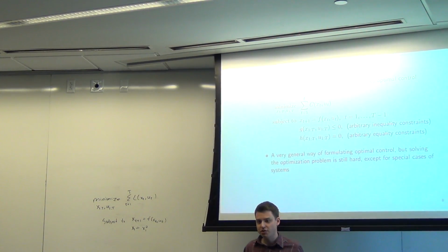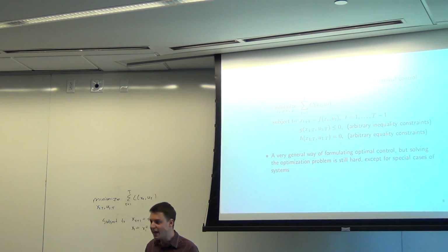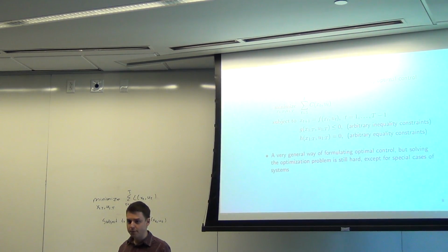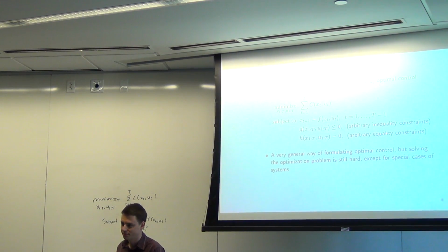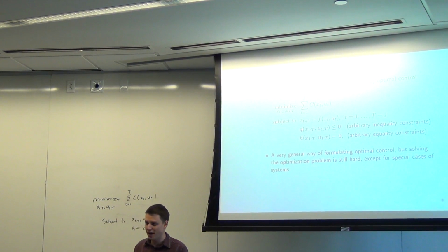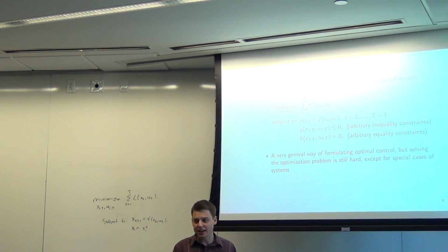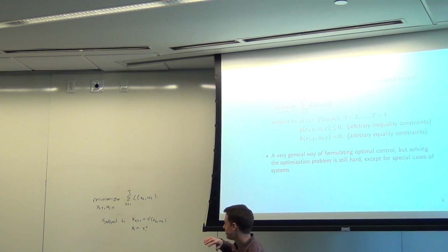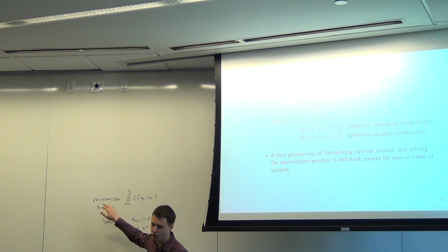This is very similar to what you do in power flow, or optimal power flow, where you let everything be a variable in our optimization problem. But most of those are actually going to be fixed by the constraints of the system. So you have some variables, but they're not really variables, maybe. But if you were to type that into YALMIP or any other solver, it's much easier to write it this way than it is to write it the way that removes all these variables and just writes it in terms of the u's alone.